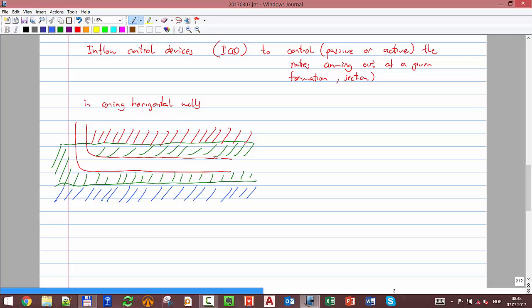The thing is that if you plot the permeability along the wellbore, okay, in that case the horizontal permeability along X, you might have variations. Okay, you might have some heterogeneity along the wellbore. So that means that if you have a very high value at this point, maybe the water will tend to cone to the wellbore, because, let's say, that's kind of the resistance.